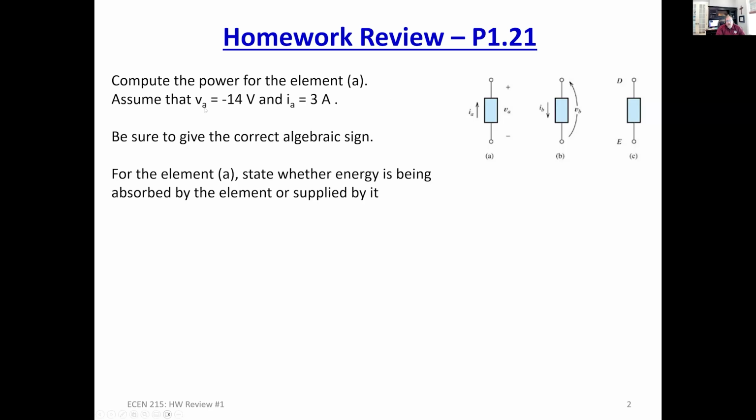So they're going to give you these using sign conventions. They're going to give you the voltage values, and obviously the value of the voltage could be positive or negative. And the same thing with the current. The current, based upon the listed terminals and or arrows defining the analysis direction, could be positive or negative. For instance, IA, which in this case was listed as minus 3 amps, means that given the direction of the arrow we're analyzing for current going this way, but in all actuality the current was traveling the opposite way, so hence it would be negative.